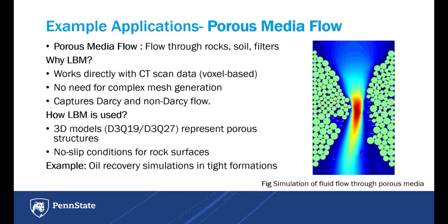One of the strongest uses for LBM is in porous media. It is particularly valuable for simulating fluid flow through rock, soil, or filtration media. LBM can work directly on voxel data from CT scans, making it easy to model real rock microstructures.